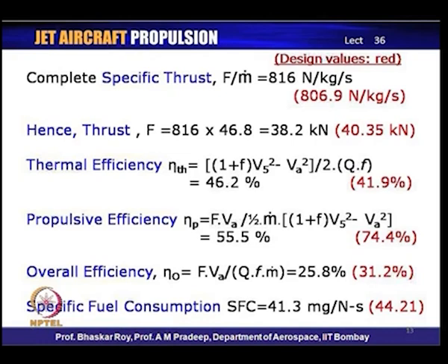Next, we can find the propulsive efficiency, for which we use the definition that we introduced earlier in this lecture series. That is the actual thrust work done by the engine, F into V_A, compared to the energy that is available with the gas, which is the exhaust energy minus the entry energy, which we used in the earlier definition in the numerator, and that now comes in the denominator, multiplied by the mass flow.